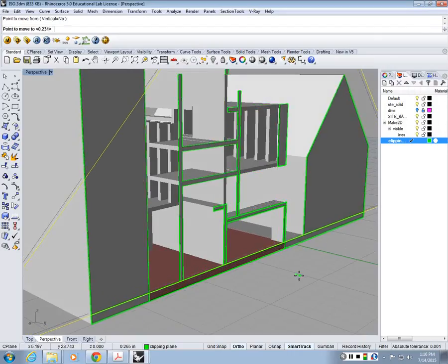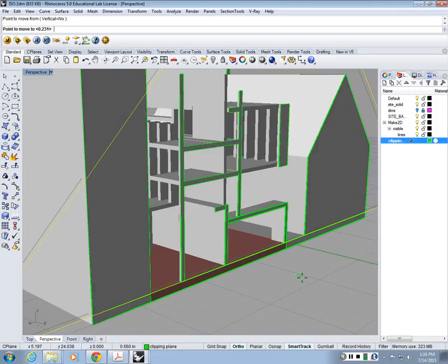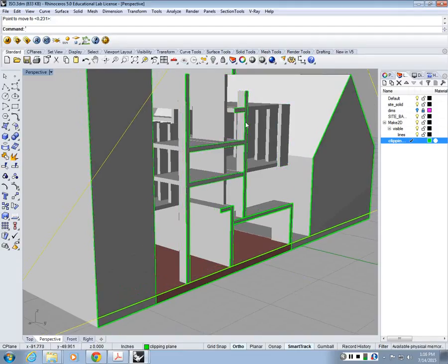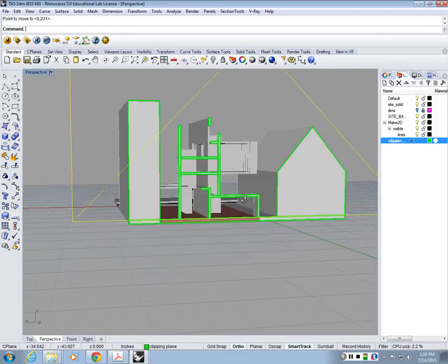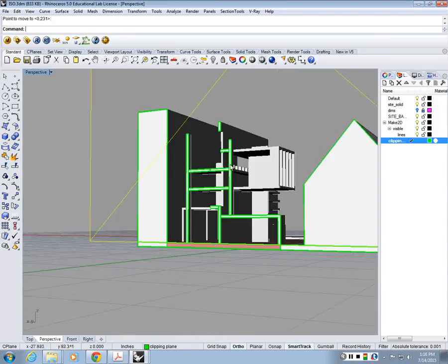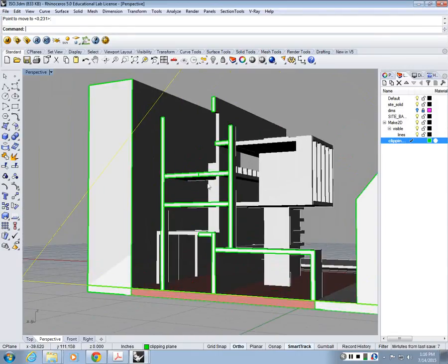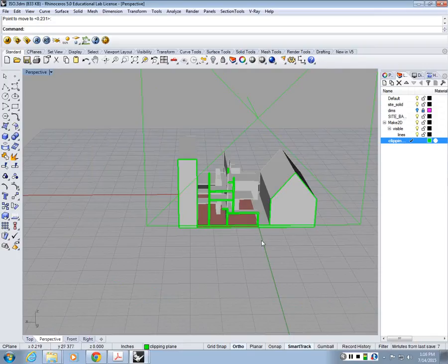You don't want to cut columns perpendicularly. You never draw sections through columns. Okay? So I'm regarding that as a column. But these are continuous walls, so inevitably I have to cut through some of them. So I'm making a compromise, like cutting through this one and seeing these openings basically. So this is the section I want to draw.